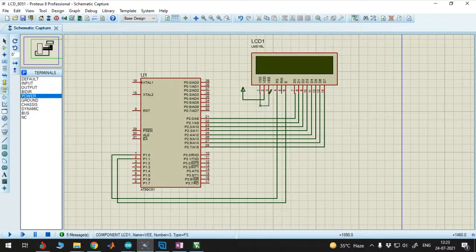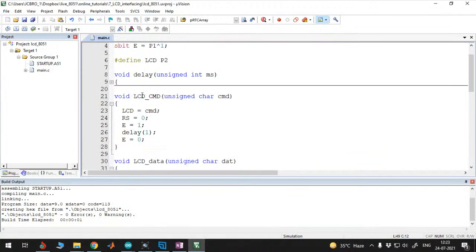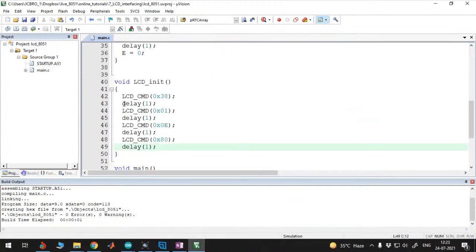So first of all, we'll connect this, and then we'll take a ground here, and then we'll connect it. Okay, yeah, now it is fine. That was the problem because ground was not properly connected. So let's try to avoid this extra delay which we have created, because sometimes if we are not providing enough delay, LCD doesn't work at all.